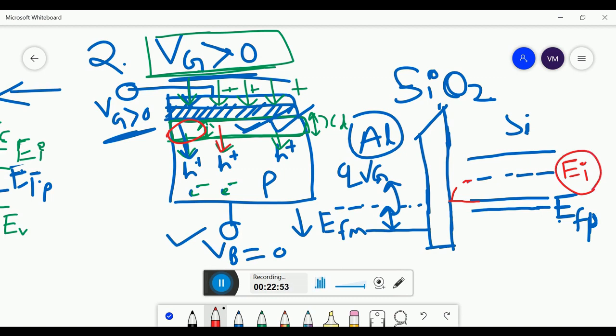So what happens in original silicon? In the original silicon there is no free charge carrier because it is not doped. So it has neither holes nor electrons. The same condition appeared here. It is depleted of any charge, so there is no charge carrier here, and it behaves similar to an intrinsic semiconductor. In that case, the intrinsic level should come closer to the Fermi level of the silicon. This is the Fermi level of the silicon, and it came closer to the intrinsic.